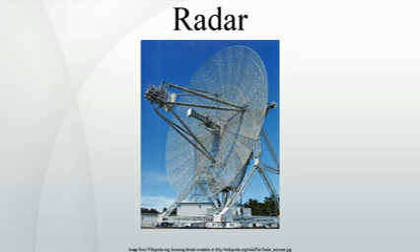liquid coolant with minimum pressure and flow rate is required, and deionized water is normally used in most high-power surface radar systems that utilize Doppler processing. Coolanol, silicate ester, was used in several military radars in the 1970s. However, it is hygroscopic, leading to hydrolysis and formation of highly flammable alcohol. The loss of a U.S. Navy aircraft in 1978 was attributed to a silicate ester fire. Coolanol is also expensive and toxic.